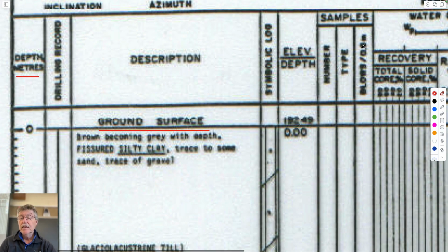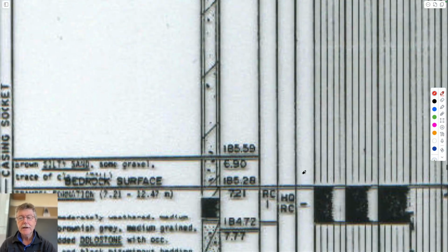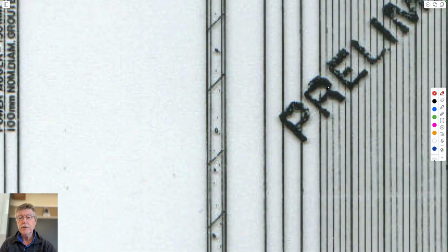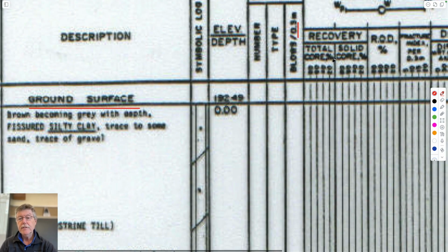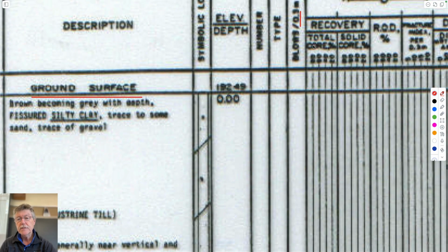Yeah. If you are drilling with the split spoon, this is how many blows per foot. 0.3 meters is a foot. Metric magnitudes. None taken within the soil. And then for the core that is taken out, you can't see this very well, but this is the core that's recovered. This is 20, 40, 60, 80, 100%, I think, in that order. So this is how much core you recover, how much is solid, like in the Gobi Desert, one piece of core being 3 meters long, just amazing.